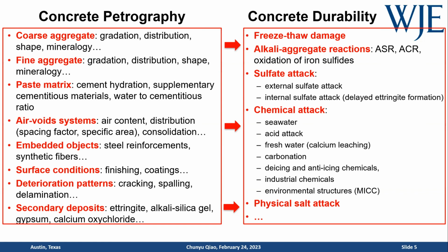Gypsum is an important one for sulfate attack and biogenic attack in sewer environments. And another very last one, but not the least one, is called calcium oxychloride, which is an important secondary deposit in the freeze thaw and de-icer damage we're talking about today.